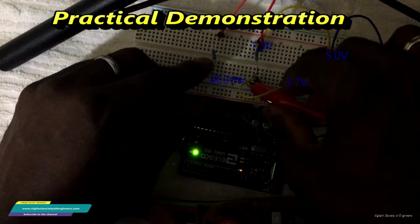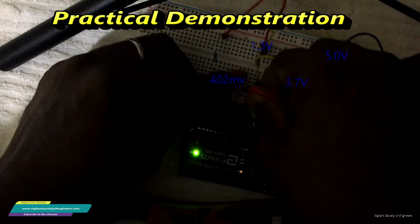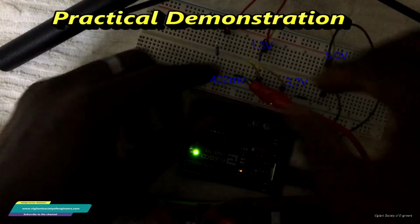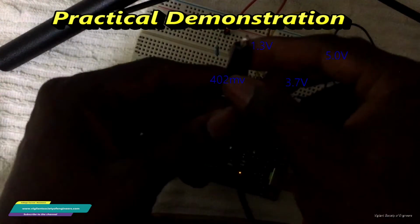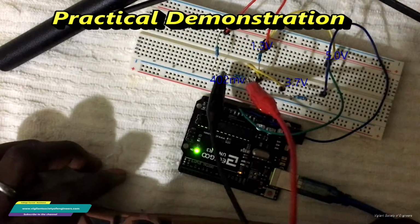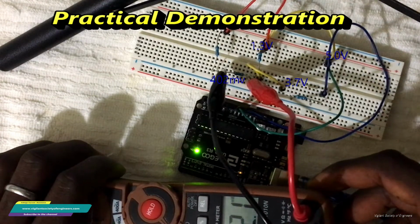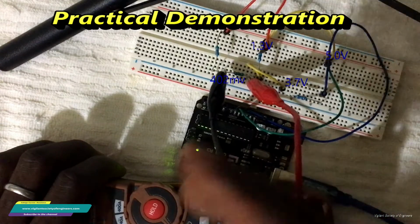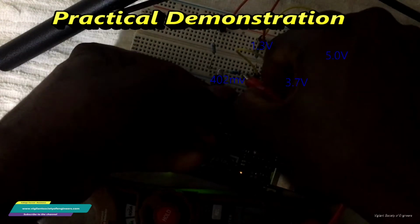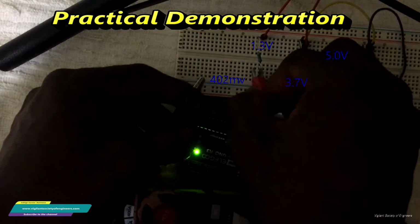We're just going to check the value though, and we're going to prove that they are equivalent to roughly 1.3, even though we have received almost 1, right? But as we're saying, there's experimental loss that will occur in the circuit. So I'm getting roughly 0.3 on one side, right? That is across the 100 ohms. So I'm getting roughly 0.3, and then I'm going to measure across the 220 ohms.